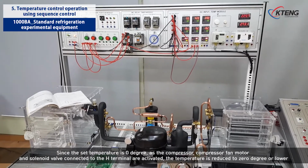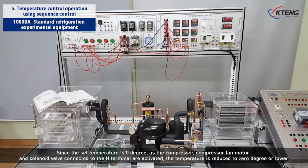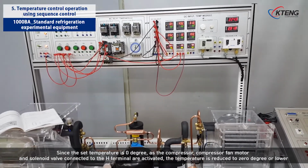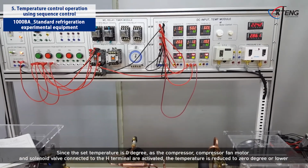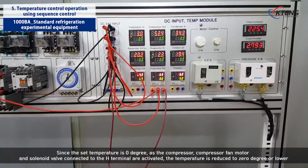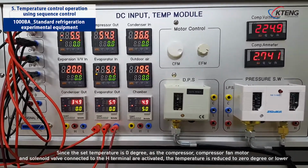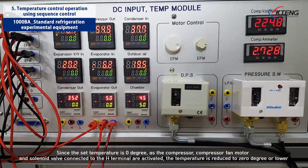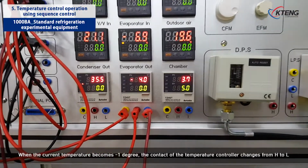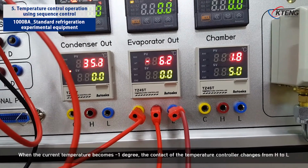Since the set temperature is 0 degrees, as the compressor, fan motor, and solenoid valve connected to the H terminal are activated, the temperature is reduced to 0 degree or lower. When the current temperature becomes -1 degrees, the contact of the temperature controller changes from H to L.